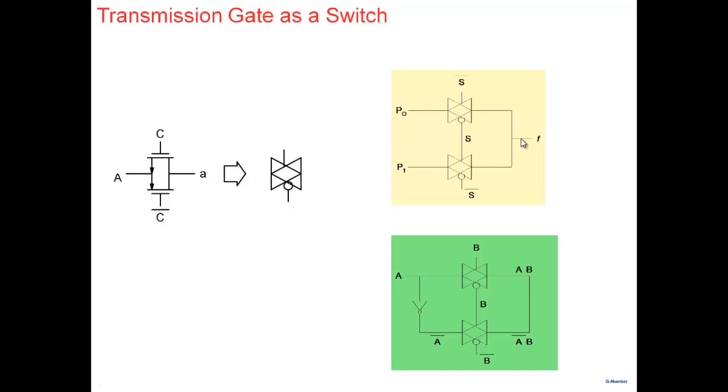If at the output of each one I put an inverter, then there is no such long chain. It will never happen. But then it becomes more complicated. Each one of them has one more inverter attached to it. So that long RC transmission line will never happen because every time there is an inverter in between.